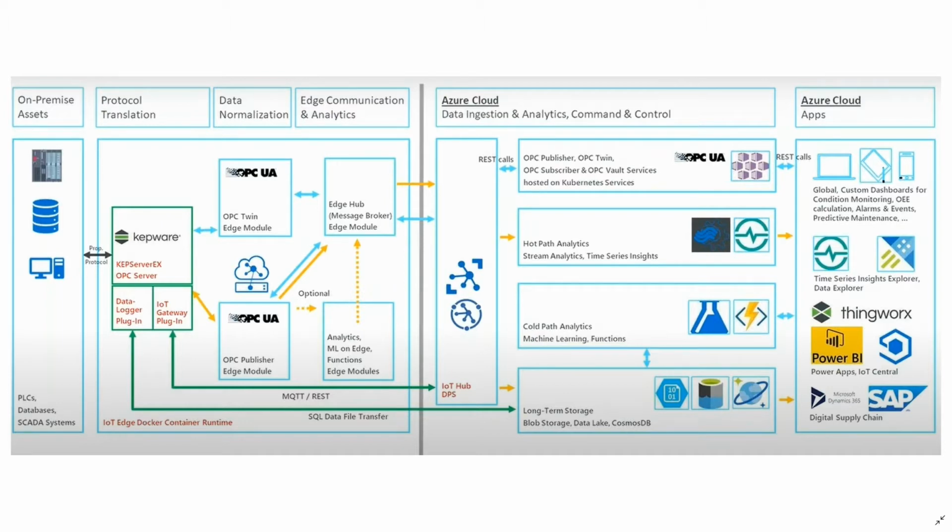Kepware has multiple ways of passing data to the Azure cloud platform: via the IoT Hub, via the long-term storage, and using the IoT Edge Docker container runtime, which is actually running on premises downway of the Kepserver setting. In our demonstration, we will deal with the third one, which is the use of the OPC Publisher module on Azure IoT Edge. So we can see that the Kepserver is the OPC UA server,